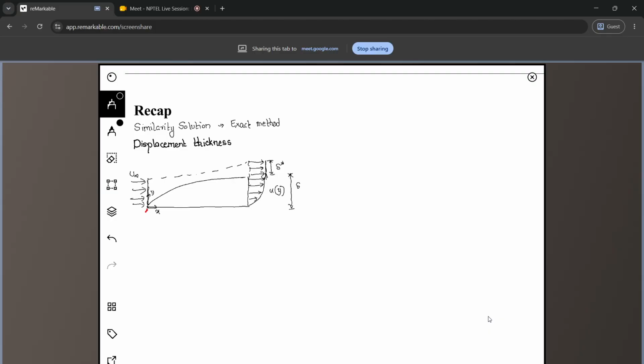At the inlet, that is the integral of rho u infinity dy from 0 to delta, which should equal the integral of rho u dy from 0 to delta, plus, from delta to delta plus delta star, where again the velocity equals the free stream velocity, the integral of rho u infinity dy.